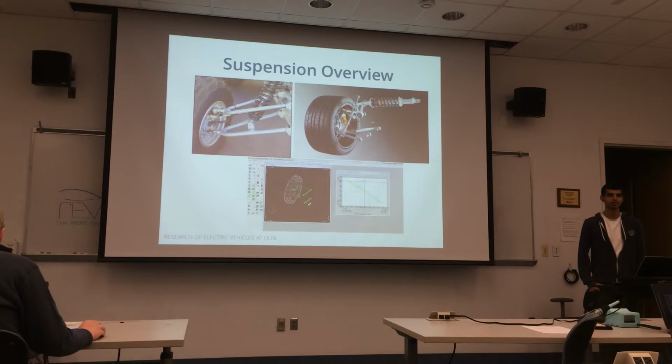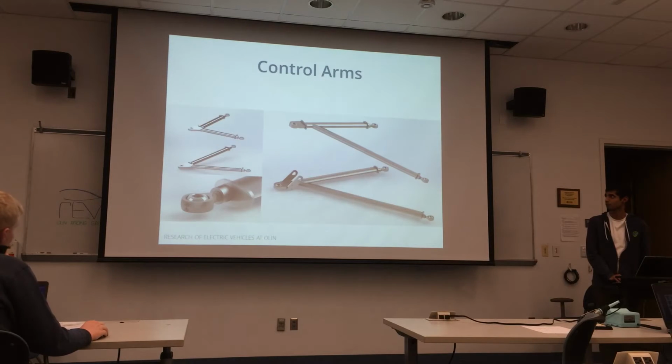You want more weight on the main body of the car, because this is going to be supported by the springs, and this gives rise to more consistent vehicle behavior, which is why we do what's on the top right, which is called a push rod suspension, where your shocks are mounted with the body of the car and then connected by a smaller rod down to the wheel. This makes sure the bulk of the weight is with the main car and gives very consistent handling compared to normal suspension.